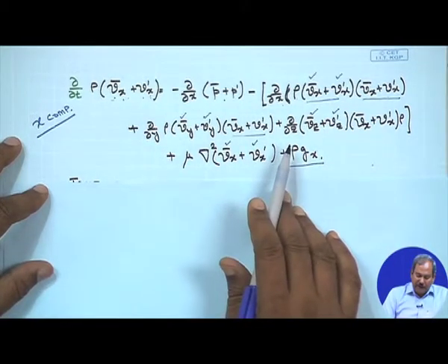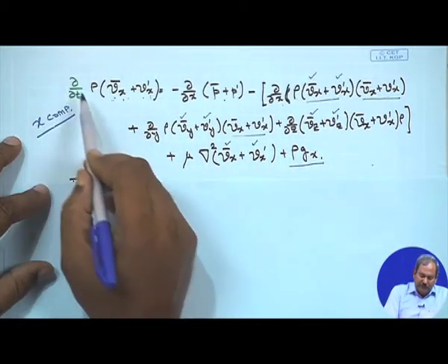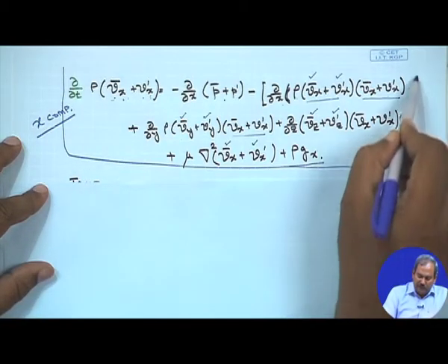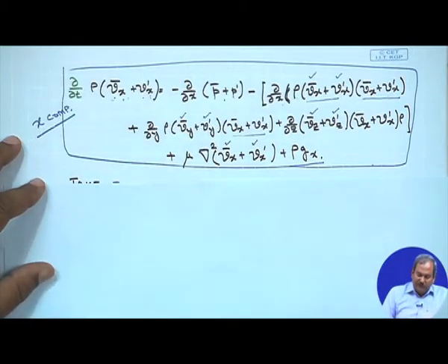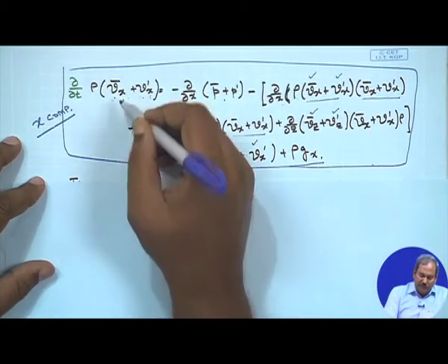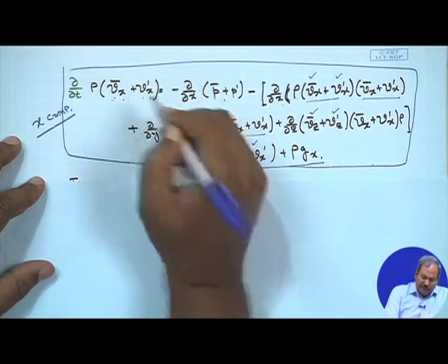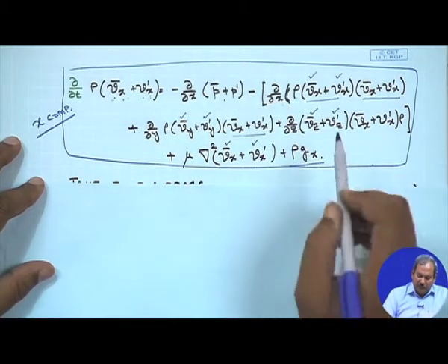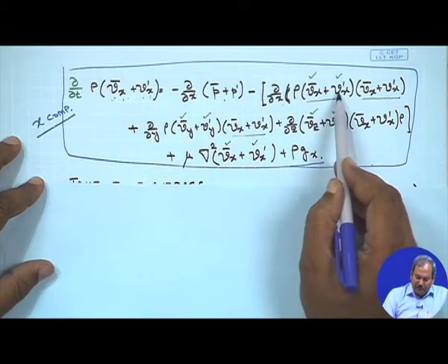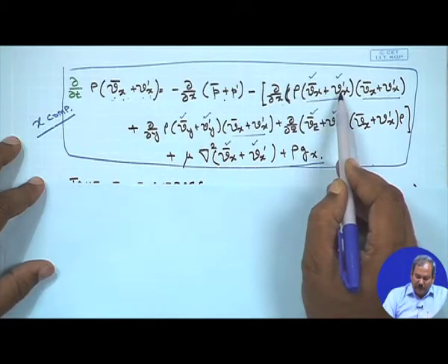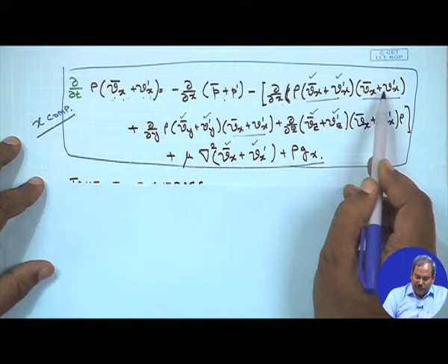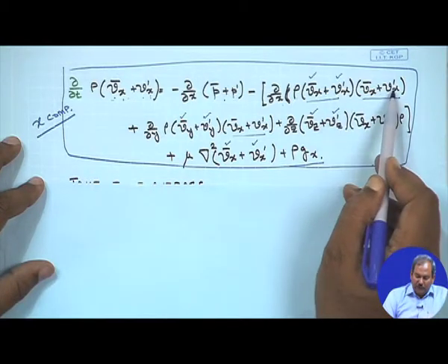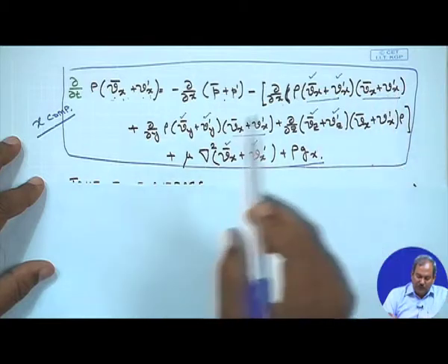What we do at this point is we take a time smoothing of the entire Navier-Stokes equation. So if we take the time smoothing of this equation, then obviously this term would disappear, this term would disappear. Wherever I have v prime x alone, it will disappear, but here you would see you have a v prime x square, and the time smoothing of that would not be 0.